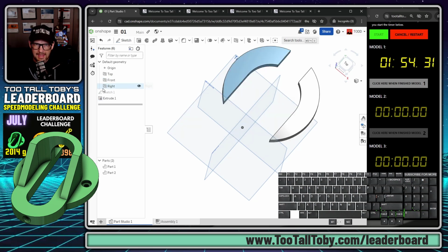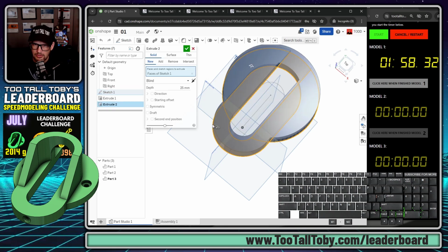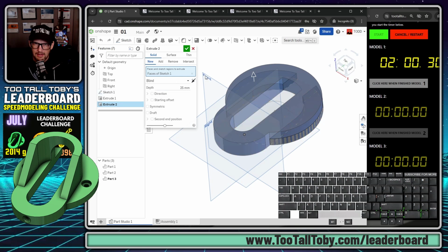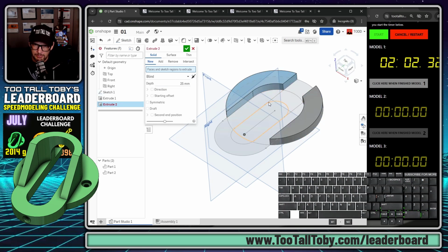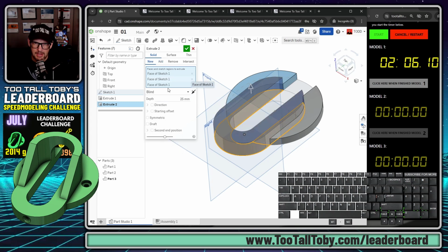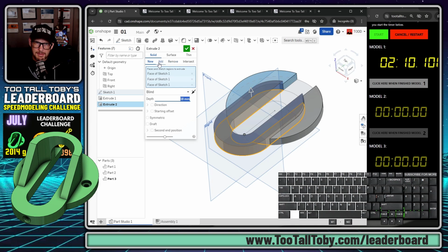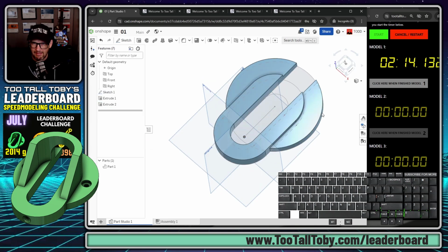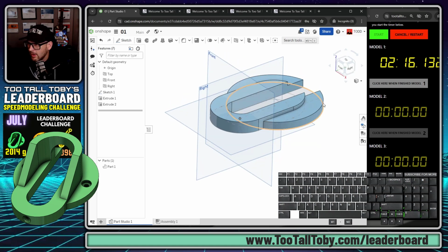And then I can show that sketch and use that sketch again, just select on it and use that sketch again. And now we're gonna take this remaining geometry. So press the space bar to clear what you don't want. I'm gonna take this remaining geometry here and bring that up to a height of 18 millimeters. And this is gonna be an add, and I'm gonna say merge with all. And that way I'm taking that layout geometry and merging it across to everything.